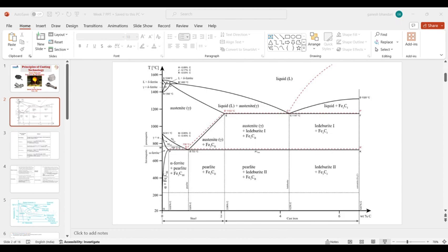Okay, we are going to put the sample in heat treatment furnace. We are going to get the temperature, put it in heat treatment furnace according to our required temperature, and after giving the heat treatment process for some time, we are going to take that sample out from the furnace, and we are going to put it in air to cool down. Okay, so that will be your normalizing process. So in case of normalizing heat treatment, you are going to get some ductility, more ductility in your sample. You are not going to get hardness in your sample.